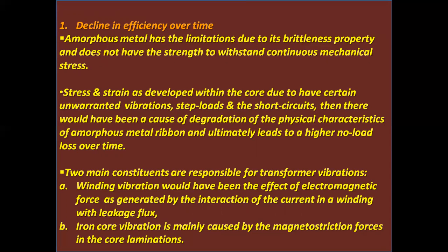Stress and strain developed within the core due to unwarranted vibrations, step loads, and short circuits cause degradation of the physical characteristics of the amorphous metal ribbon and ultimately lead to a higher no load loss over time.